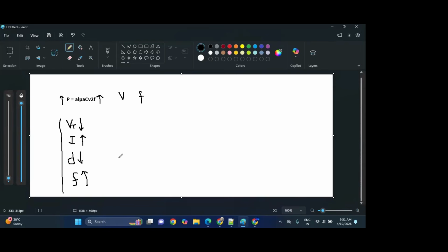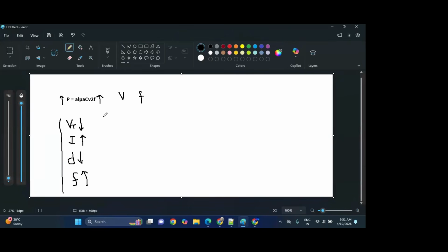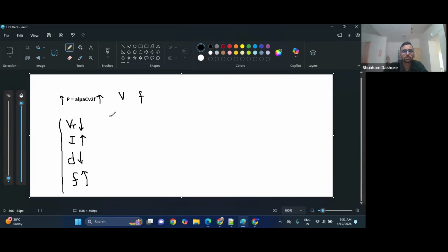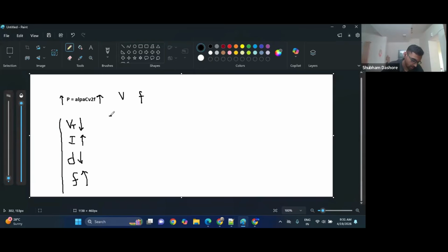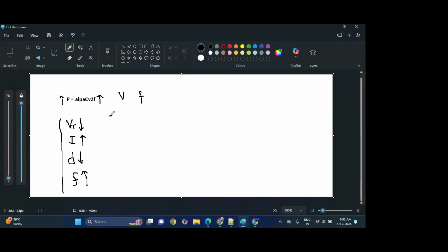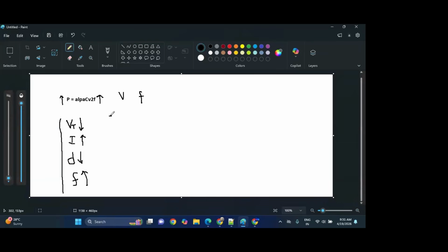Okay, you know the power formula? The complete power formula is alpha half C V square F plus I_SC, short channel effect, into voltage, plus I leakage into voltage. So this is the complete formula. You can write it also. That I asked in the first question, fine?